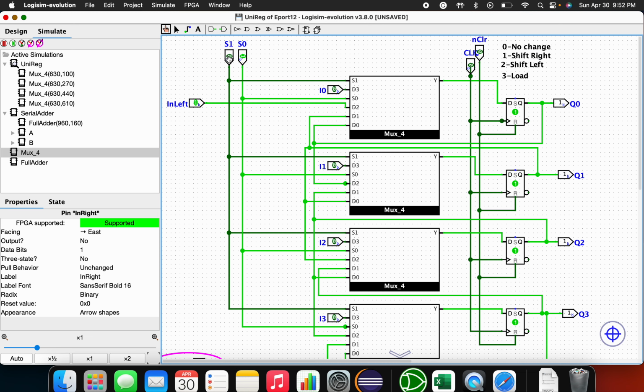And then we can move on to the next mode, which is going to be shifting left. It's going to be moving to the most significant bit. Let's have a 0 for demonstrative purposes. So clock pulse, moving down, and then we can demonstrate the serial load. 1, 1, 1, 1. And now these are all 1s.